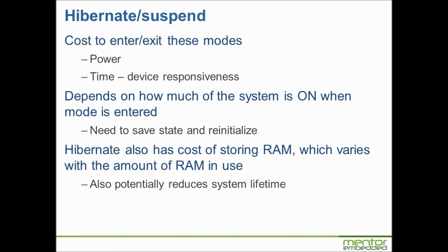A little bit of a worry is system lifetime. Flash memory withstands a certain number of cycles of use. Now, you can do wear leveling and all kinds of clever things to maximize that, but there are limitations. Modern flash has much better lifetime than it used to have, and I was only reading this week about some technology for revitalizing flash chips and giving them even more life.